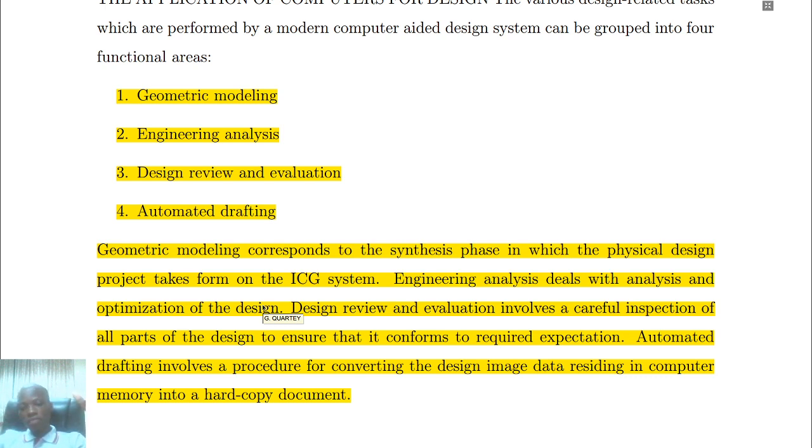So you may carry out that finite element analysis on it. You may carry out that fatigue analysis. Then with that, you'll be able to tell that, oh, with this shape and this design that you are having, when it goes through this particular cyclic loading for this number of times, it is going to fail, and this is the point it's likely to fail at.